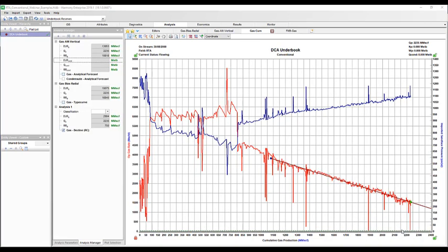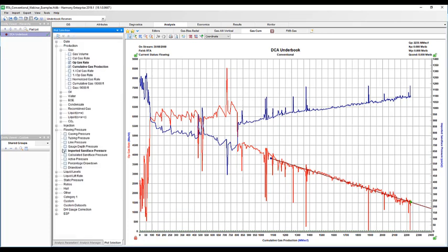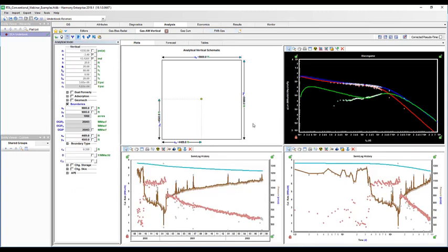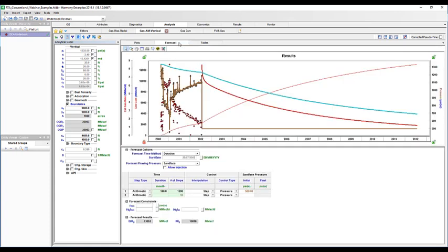So to see what upside potential there could be from this well, we have done some modelling and history matched the production, as you can see here on our analytical model. Now that it's history matched, we can try some what-if scenarios with the forecast to see if we can improve production. One scenario would be if we can lower the back pressure of the well, say by wellhead compression, and see what the resulting forecast would look like.